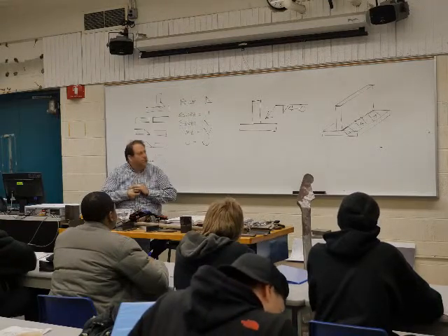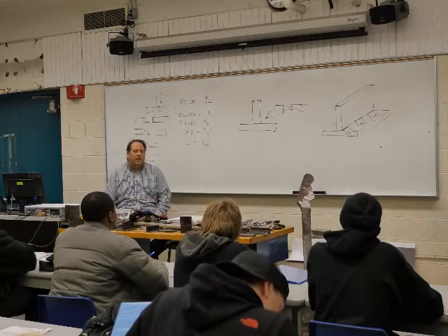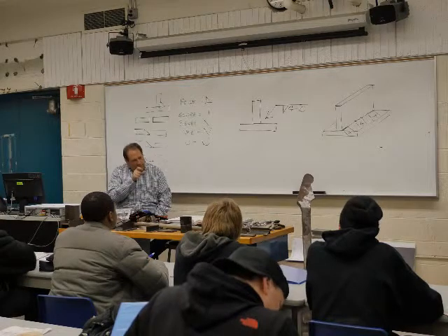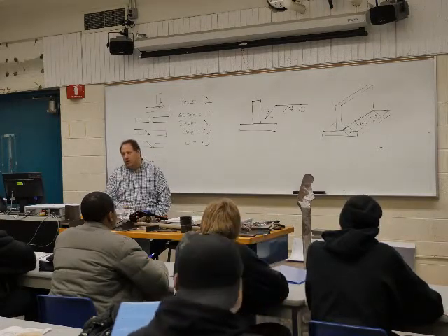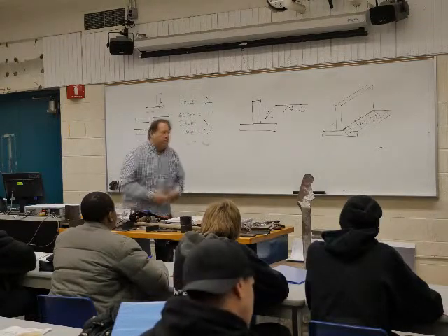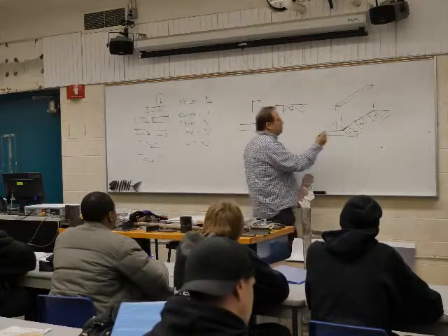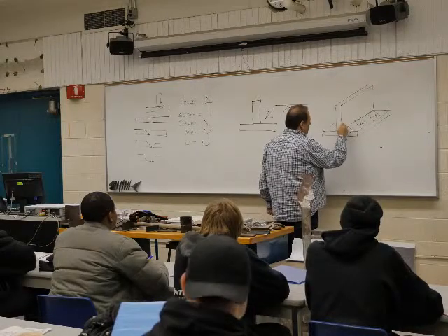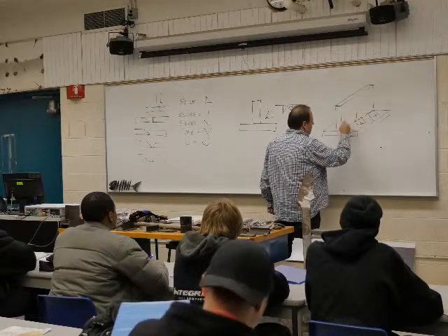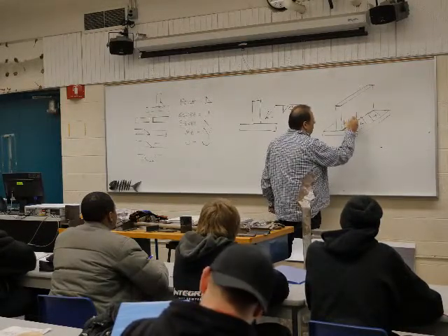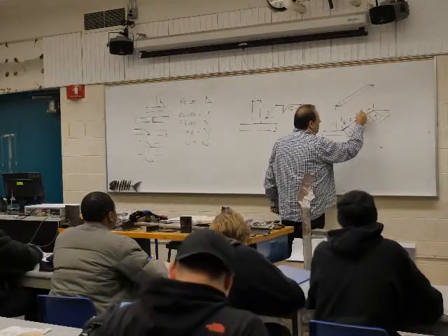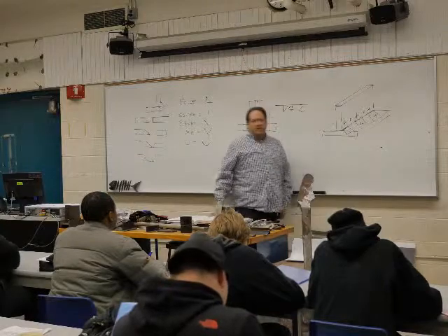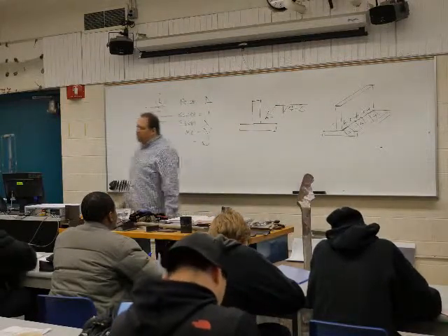But what it actually determines is not anything to do with the length of that or the gap, but it is a center-to-center dimension. So when we talk about a pitch of a weld, we're actually dealing with from the center of one weld to the center of the next weld.